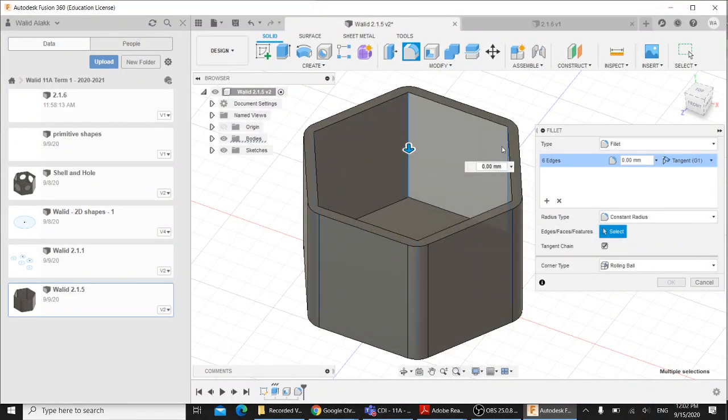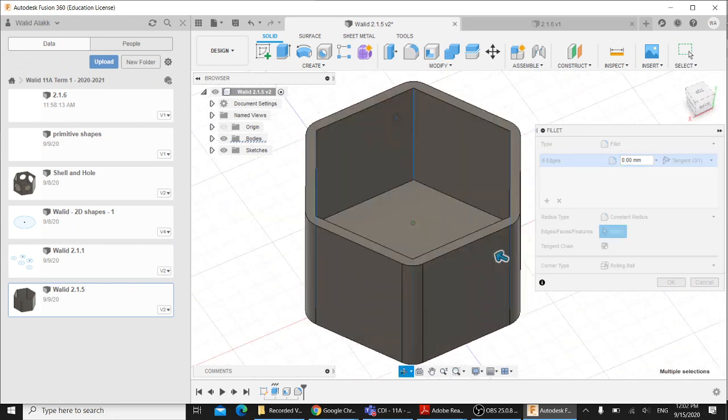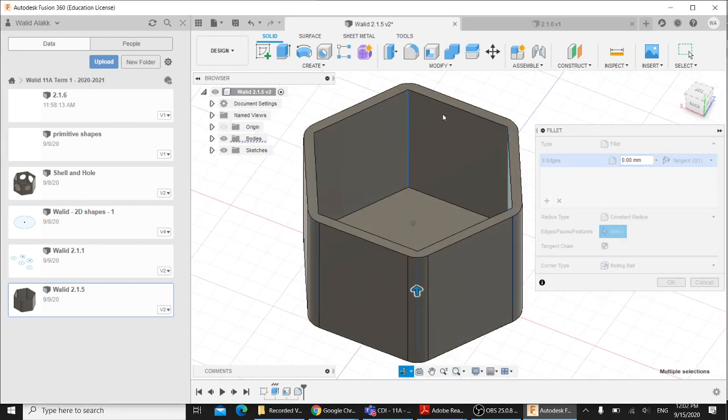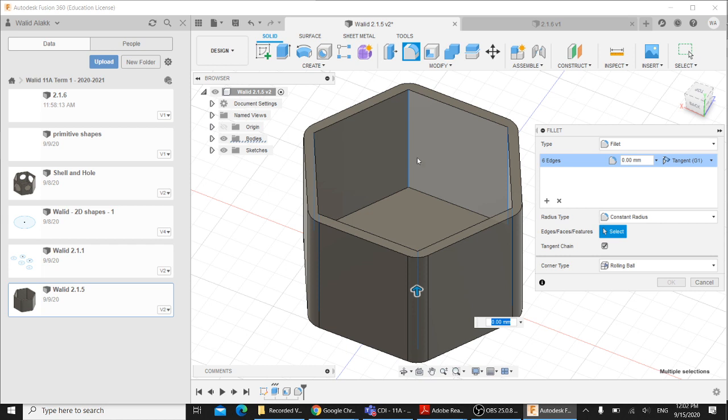Okay, so I was just telling another way how to make a fillet for the inside angles or sides. You can make it with a radius of 10, or you are free to choose maybe 15. See, it will be larger, like a half circle. If we make it 20, it will be much smoother.